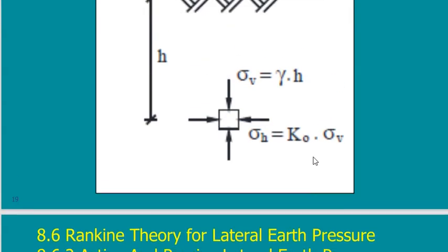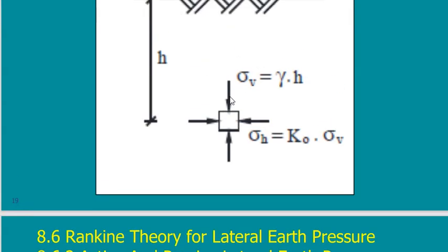Let me take it this way to understand it. This is a vertical force. Part of the vertical force will act here. Suppose that I tried to move the block of soil, I mean the confining pressure is reduced. Confining pressure means this force. Imagine that this force is 0, and I have a force here. Of course, once this block starts to move, the amount of the force will be reduced.